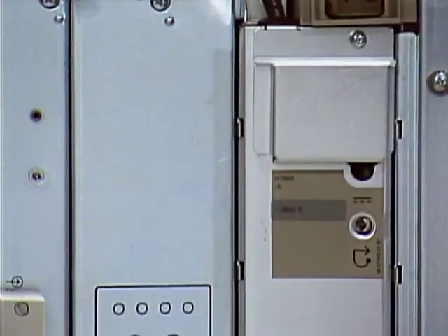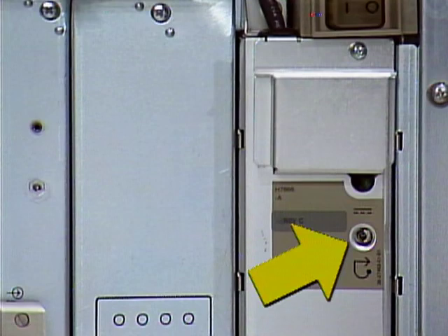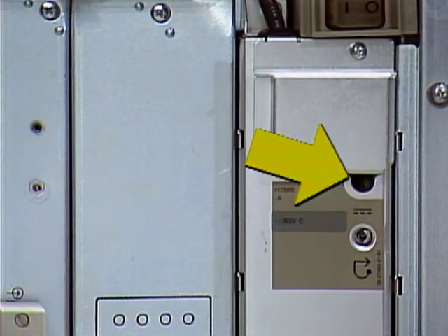A recessed switch on the front of the power supply will allow a full power-down, power-up sequence of power OK and DC OK signals without removal of the input power. This in effect resets the VAXstation 3520-3540 workstation. Each power supply has a green LED that indicates power OK when illuminated.